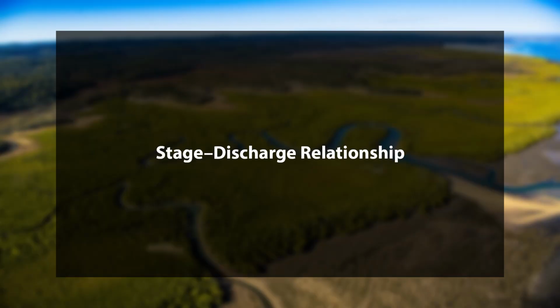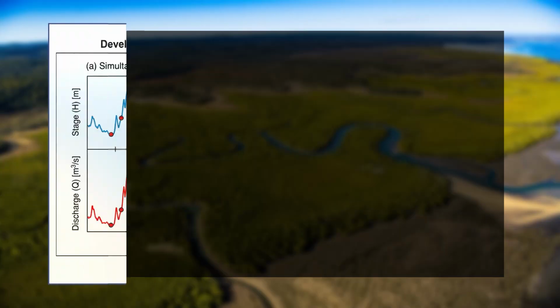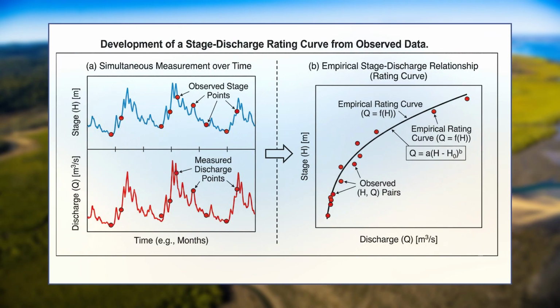Stage discharge relationship. Measuring continuous discharge data is impractical due to cost of instruments and field studies. To bridge this gap, hydrologists develop a stage discharge relationship at a known place. Both stage and discharge are measured for some time and an empirical relationship links observed stage values to corresponding discharge measurements.